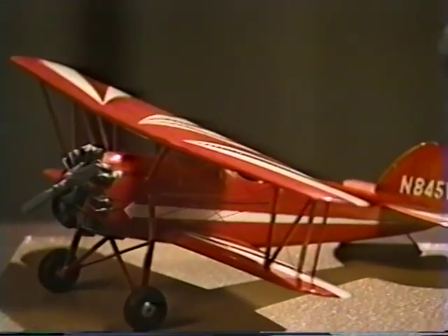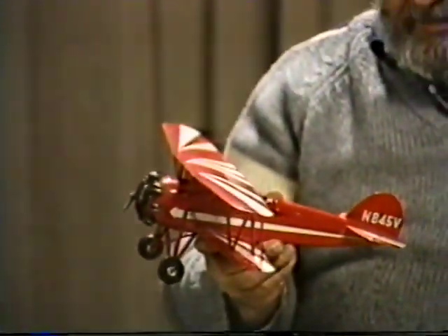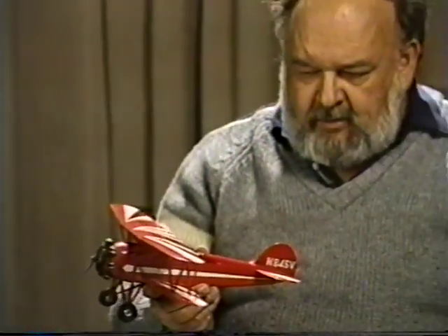If we then take a good look at an airplane and try to understand all of the factors presented in here, we have directional stability, which is accomplished by the fin itself. The rudder is the surface that counteracts this directional stability, and again, we can have as much rudder as we would really want. The more we have, the more stable it is, the better a pilot likes it. But you also must have a rudder that's big enough to counteract it.